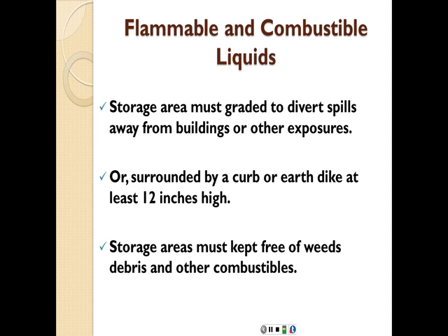Storage area must be graded to divert spills away from buildings or other exposures. So again, to allow for the natural flow of these liquids away from the building. Or surrounded by a curb or earth dike at least 12 inches high, again to prevent the spread of the leakage of that combustible or flammable liquid. Storage areas must be kept free of weeds, debris, and other combustibles that can help with the ignition.